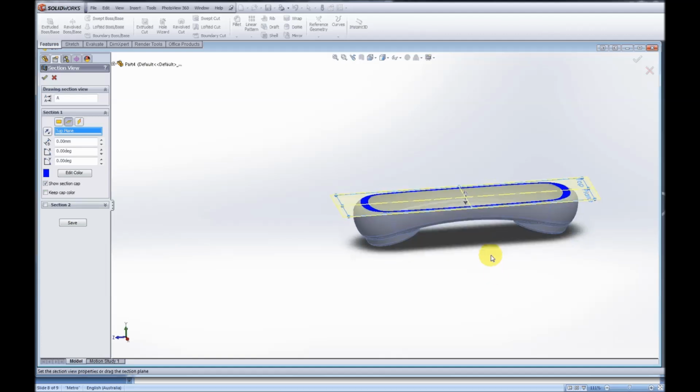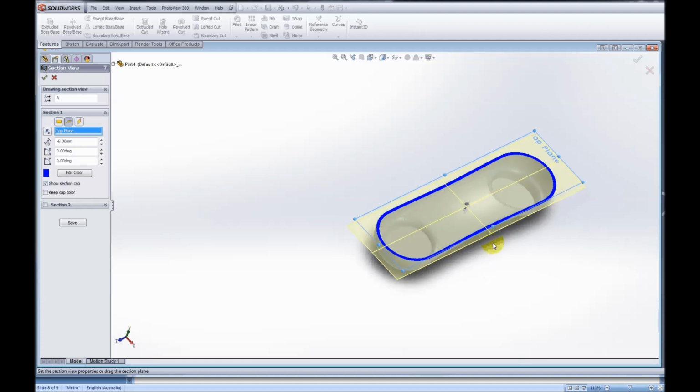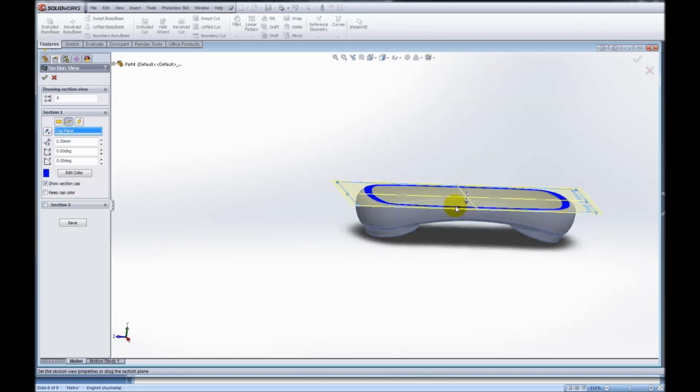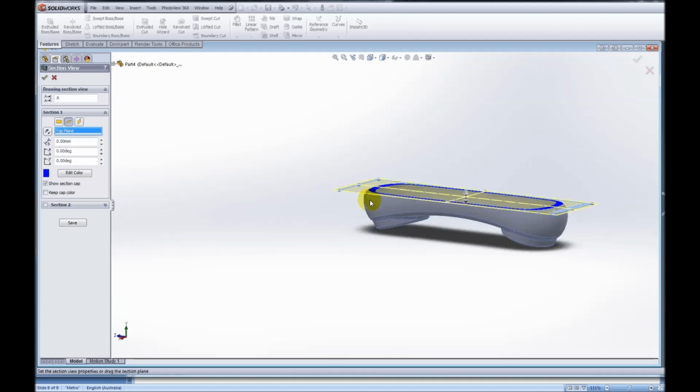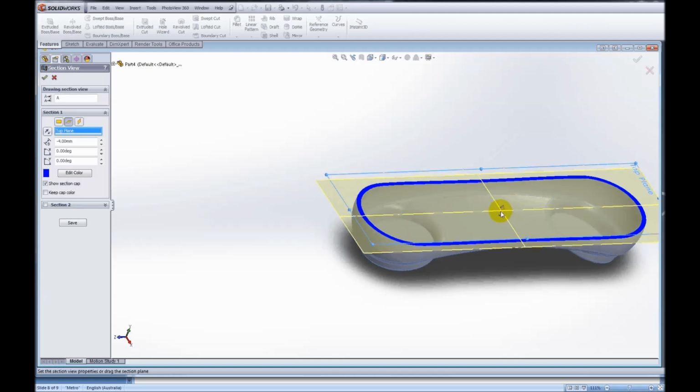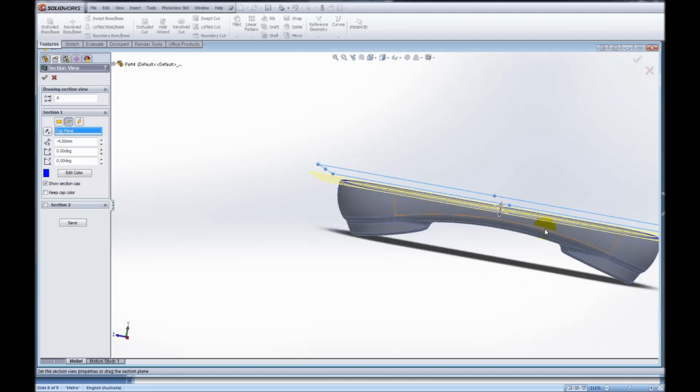The trouble with doing that is that if we have a flat split like this, we end up with undercuts in various sections of our part. So as you can see right here, there'd be an undercut in that section there, and all sorts of problems. So what we need to do is have a curved split line. The difficulty is knowing where to put that curve.